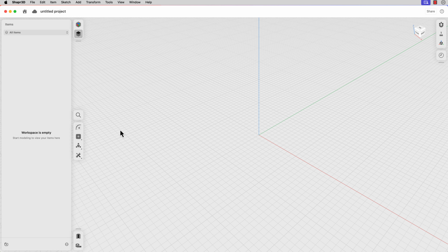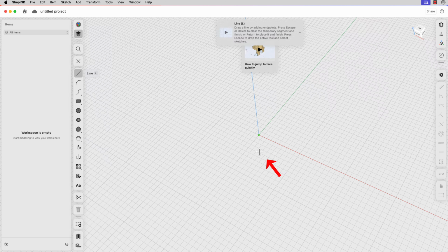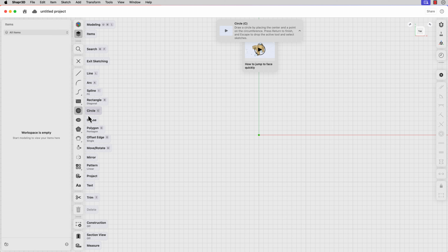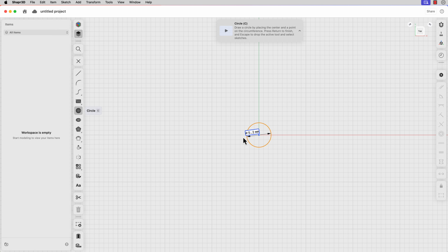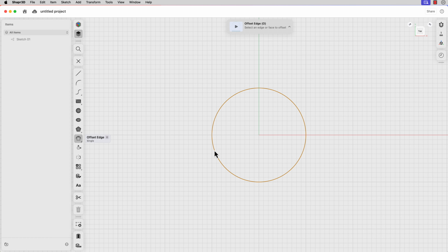Now let's make a new project. We'll start our ring project here. Let's make a sketch and choose the top plane. Draw a circle for your ring. I'll make mine an inside diameter of 20 millimeters. Yours might be bigger or smaller than that. Then use the offset command, and I'm going to use an offset for this ring of 2 millimeters. This is more of a solid, chunky design.